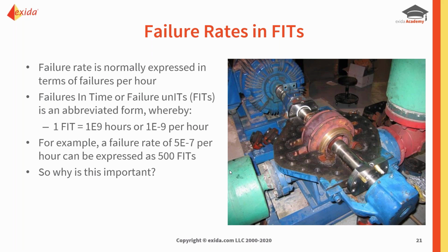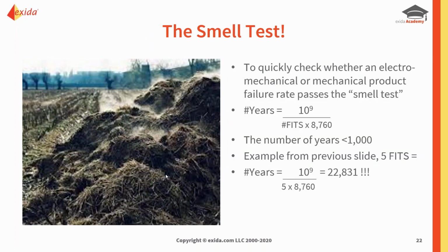So for example, if we said a failure rate existed of 5 times 10 to the minus 7 per hour, we would say this is 500 FITs. Okay, why is this important? Well, understanding what that means is very important. And this is where I talk about the smell test when I teach the class.